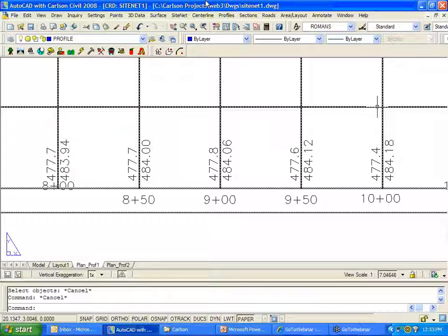In the sewer network labels in plan view, you lay out the sewer network, which I wasn't really showing you much of in plan view. If I grab that label and scoot it over where it looks good, and then there's a change to the design, in plan view it will stay. But the labels in the profile are going to be recreated. So that's a good one. We'll put that on the list for next round as well. Okay.